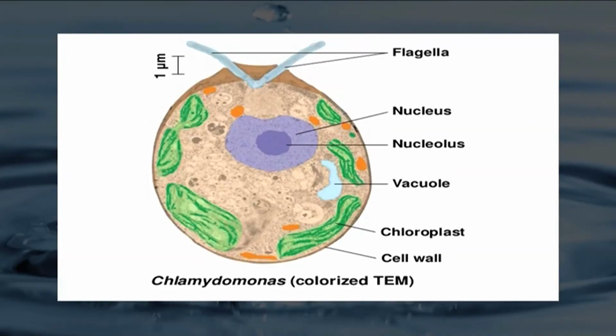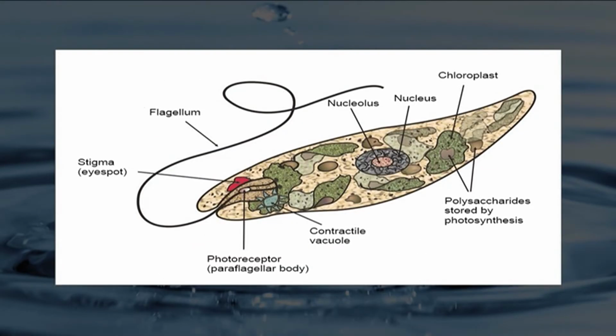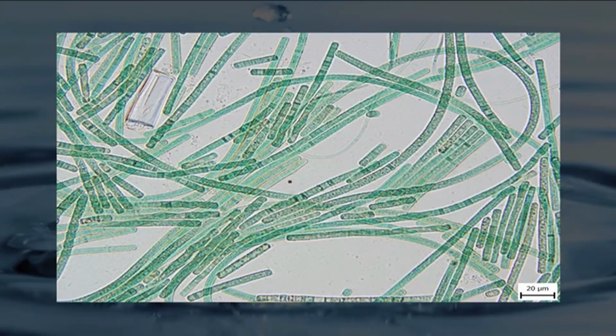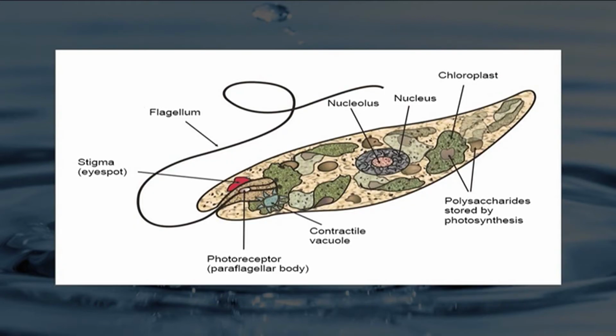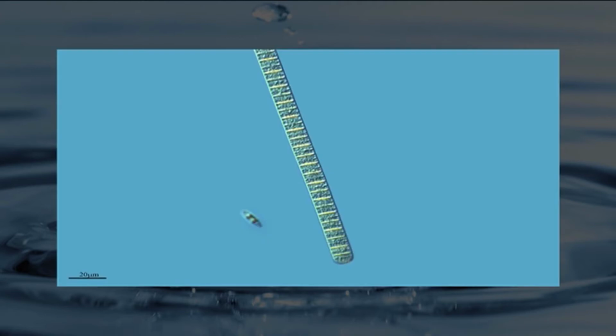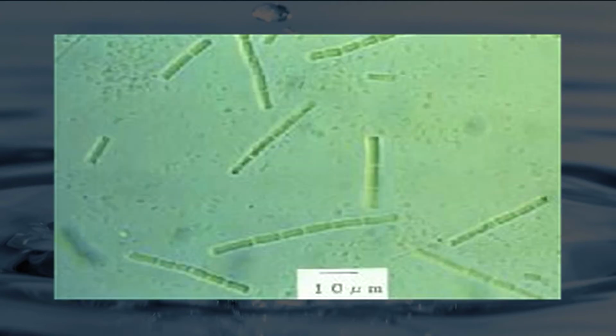Green algae Chlamydomonas and Euglena, diatoms Navicula and Synedra, and blue-green algae Oscillatoria and Phormidium are emphasized to tolerate organic pollution. At species level, Euglena viridis, Nitzschia palea, Oscillatoria limosa, Oscillatoria tenuis, Oscillatoria perornata and Phormidium ambiguum are reported to be present more than any other species in organically polluted waters.